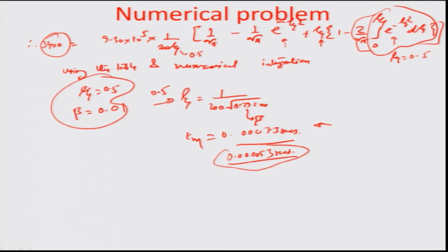So with an assumption that the surface is semi-infinite, obviously it resulted in a much smaller time frame for the machining to have happened in comparison to the case where there is a circular heat beam. So obviously heat conduction plays a big role here, and the heat affected zone is very small in this particular case, with cylindrical coordinates defining the zone affected by the laser machining process. This is one of the reasons why the time scales come out to be quite different from the ideal case of assuming a semi-infinite surface.